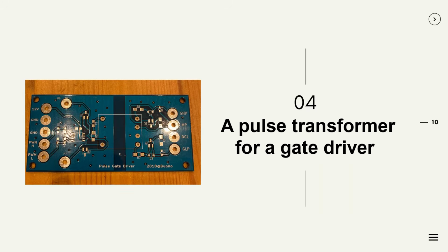The fourth and last one is this, a pulse transformer board for a gate driver. It's the circuit you use to drive a FET while keeping it isolated. And I didn't have a good board to hand, so I decided to just make one, schematic, copper layout and all, and had the board produced.